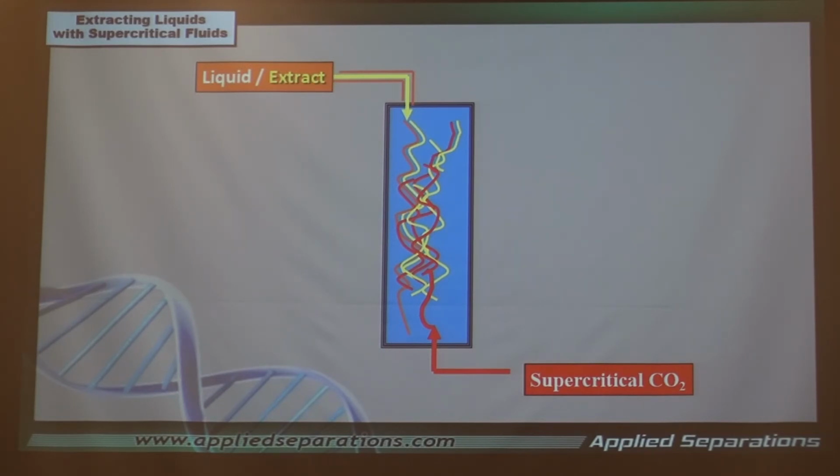Very similar to, remember in your laboratory when you have a separatory funnel. So you're shaking the tube. Now you get mixing, and we're doing the same thing. We're doing exactly the same thing. The liquid, however, is moving down this way. Now, if there's a greater propensity or a greater opportunity for the solute to be dissolved in CO2 than in the solvent, then it's going to move into the CO2, just like in a separatory funnel. We're doing the exact same thing.